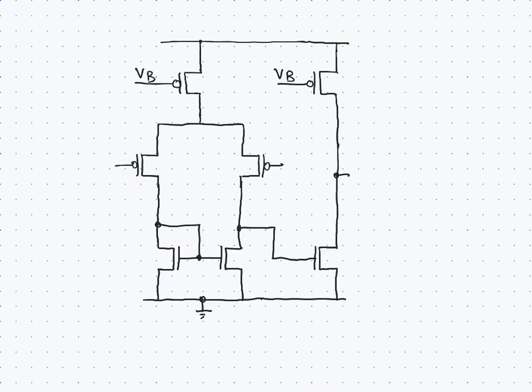So here we have, for instance, a conventional continuous time comparator, which is just the op-amp circuit we have been looking at earlier, where the compensation network has been removed. Since the comparator would normally drive digital gates afterwards, it is quite common to put a buffer stage on the output of a comparator.